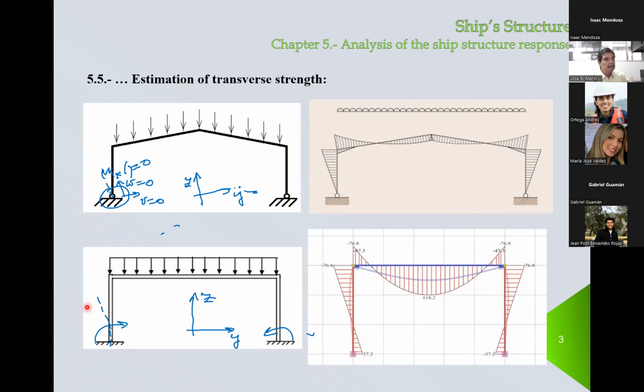In here, dM/dz is equal to a constant. If you integrate that, then the bending moment will vary linearly up to here. And then you have a quadratic variation because of this double integration of this constant. And on the right-hand side, it is symmetric to the other side.